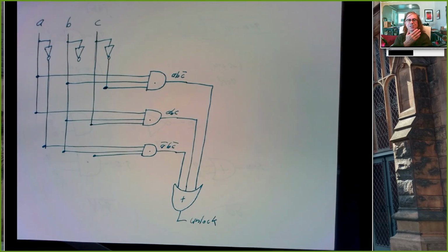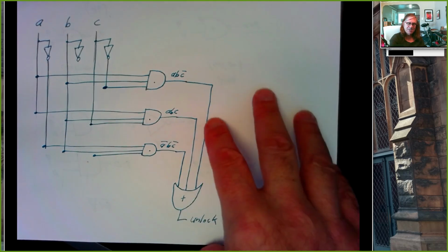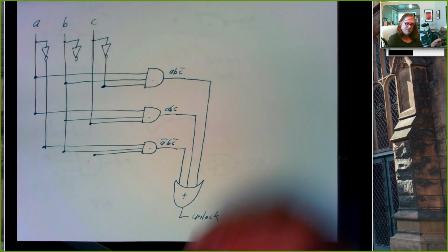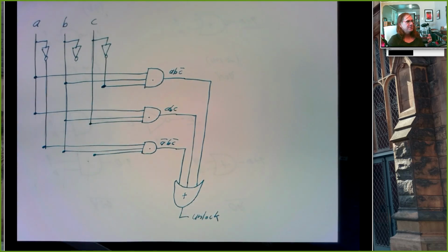So you can use this to make a circuit diagram for any sum of products equation that you have. And it's a standardized technique. All right, so I recommend using that when you're drawing circuit diagrams. And then if we were to take this and try to build it on a proto board, it's pretty easy to follow, right? Because things are kind of laid out consistently.